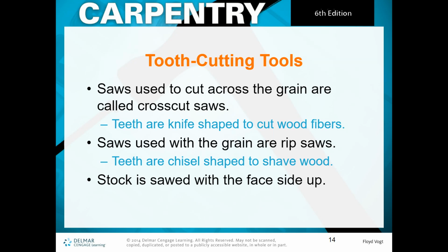Whenever you are sawing a piece of wood, you always saw with the face up. So that means that your finished face, the one that you want to see when you're done, will be the one that's facing up.